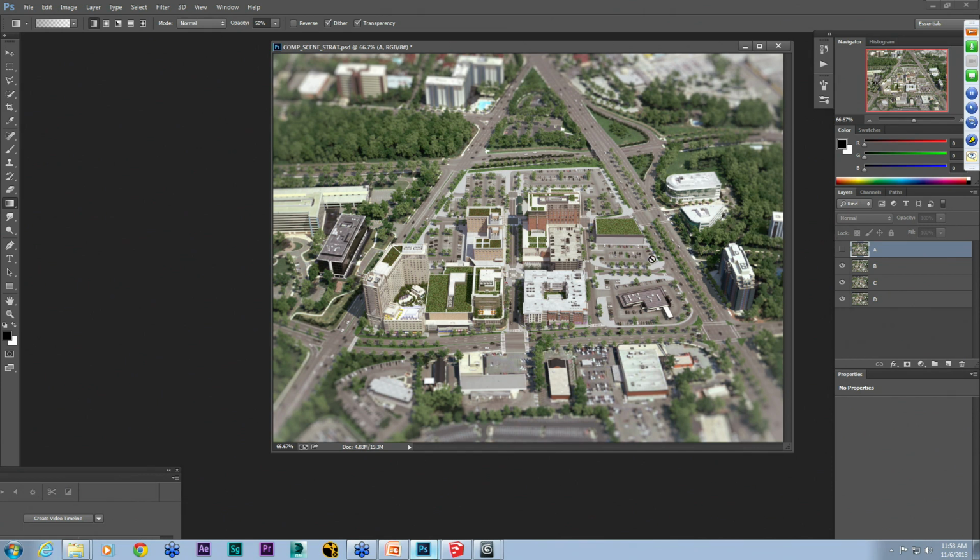We started off using all the buildings as XREFs and then all the different site phases as XREFs. And when we rendered, a lot of our plugins like Forest Pack and different things didn't render, not necessarily just because they were embedded in XREFs, but because of our particular workflow, it just wasn't working with our network rendering engine.